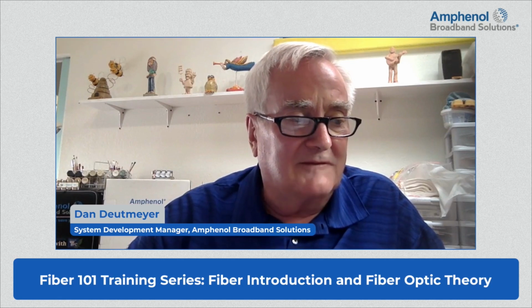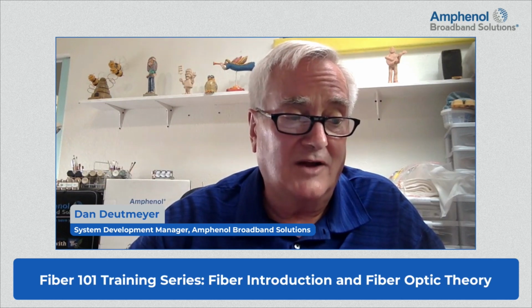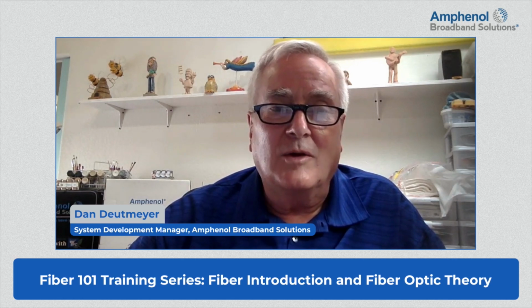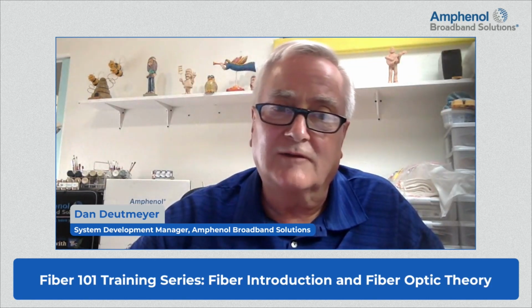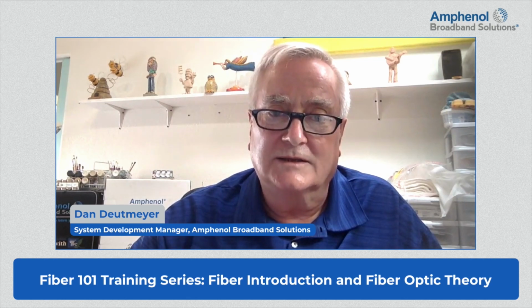The next one that we have here is, if a fiber gets pinched between the housing and the lid of a node and has high loss, will just straightening out the fiber fix it again? And that's kind of a, don't know. It could be either way. It depends on how smashed that fiber actually was. So you could just pull it out, straighten it out, look at your power level, just make sure it's not fluctuating, move the fiber a little bit where it was pinched, and make sure that it's not fluctuating.